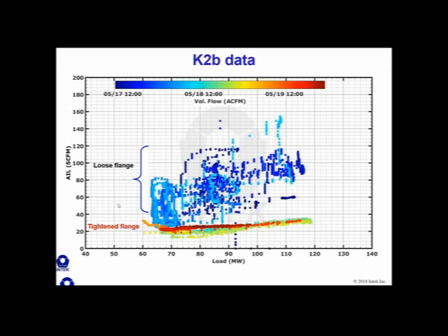Well, once the flange was tightened, here you can see on the y-axis the air in-leakage. Once the flange is tightened, the air in-leakage is at a nice low value here. Not as low as it should be, but below 30 SCFM, much lower than the 80 to 100 SCFM that we saw when we arrived.